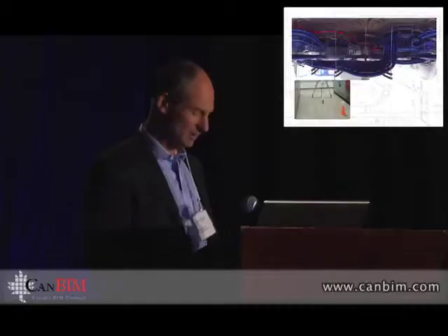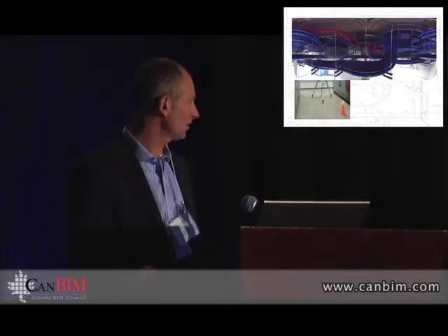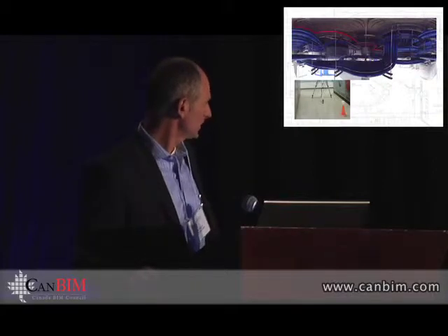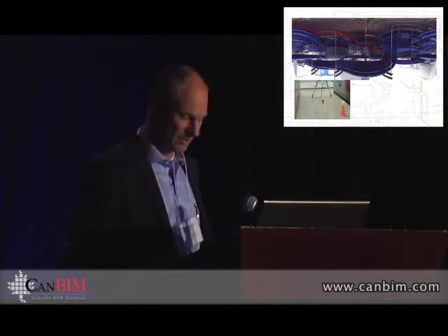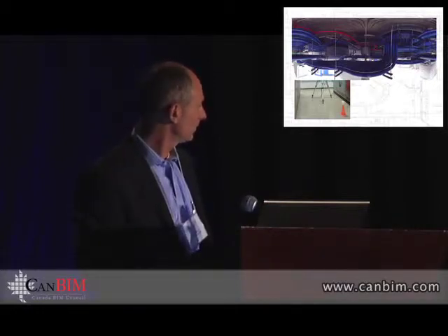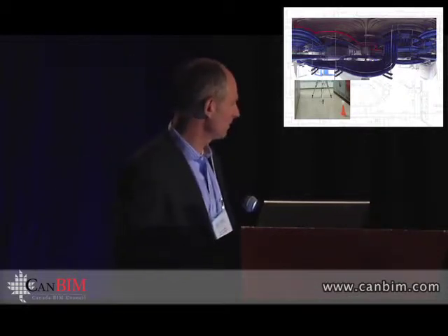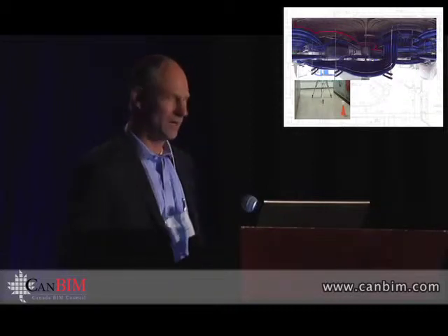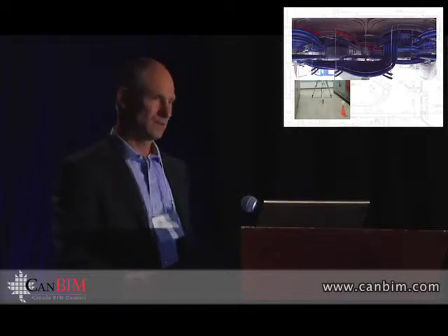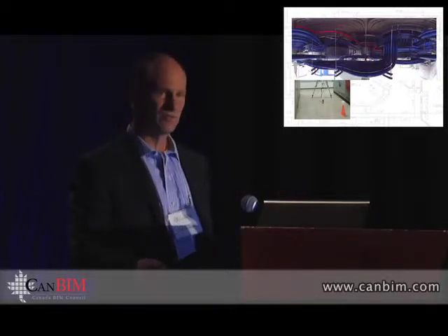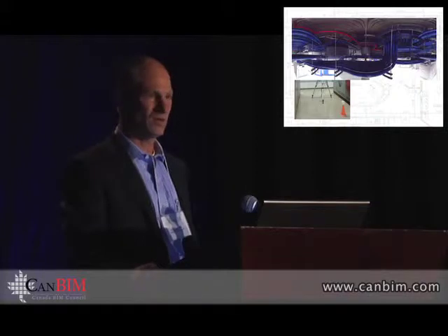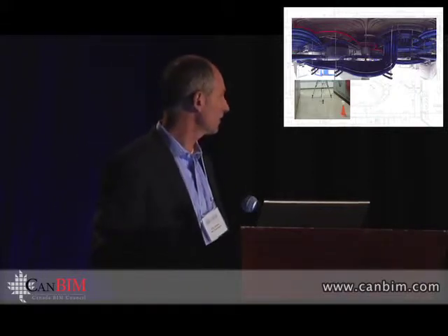This one was used, I talked earlier about the automatic targetless stuff. Here you can see they used targets to register the multiple scans together. Again, a fairly large area, quickly got all the information they needed. There's an image of a bigger tripod than the one I carry around. Quite common for contractors that are doing MEP work to want to gather all the information up above the ceiling tiles where all the infrastructural stuff is.